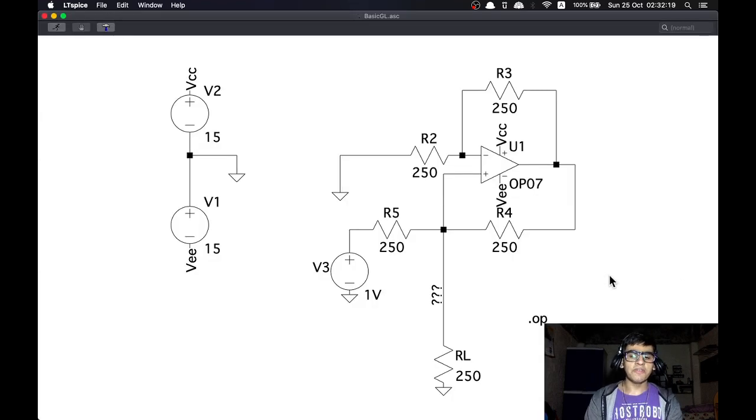So first we have here a ground load V2I converter. It is called the ground load because the load resistance is directly connected to the ground here. This configuration is independent of the RL resistor since the equation for the current through the resistor RL is given by IL is equal to Vin by R, where R is the value of any of these resistors up here. Hence, it is independent of RL.